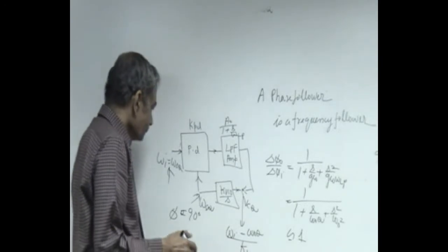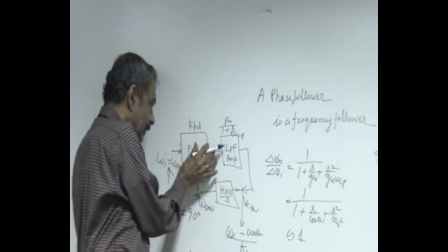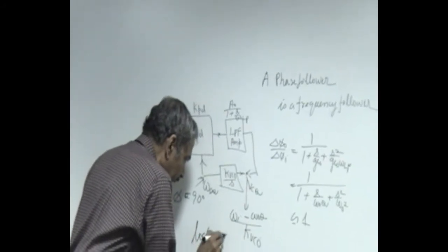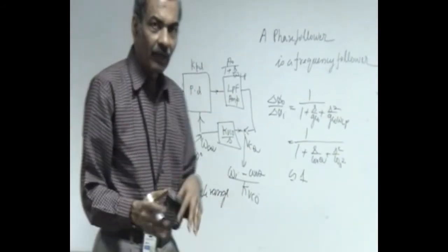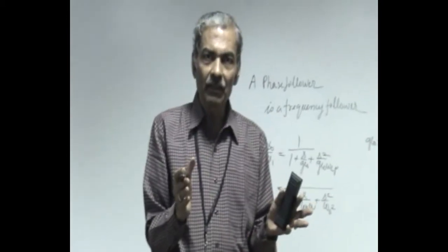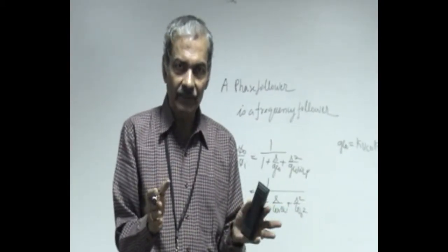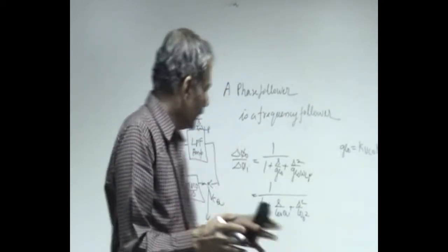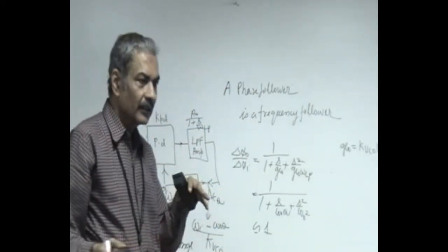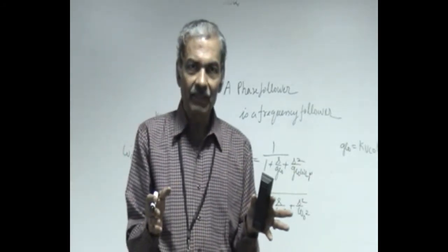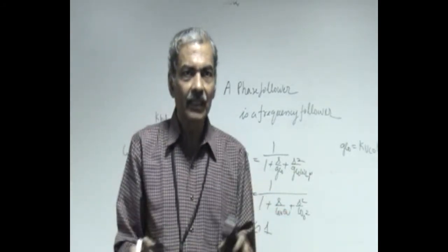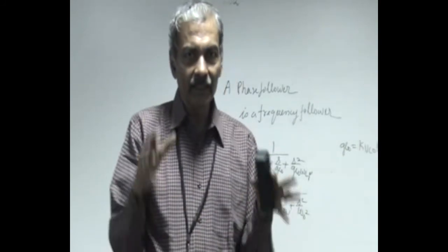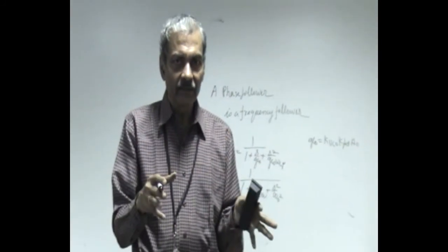This particular limit is called the lock range, beyond which it is not capable of getting locked to the incoming frequency. So please test this out. See whether your phase lock loop is getting locked onto the incoming frequency. Beyond this range, it suddenly comes back to the free running frequency. So the aim of the experiment is to understand phase locking or frequency locking.